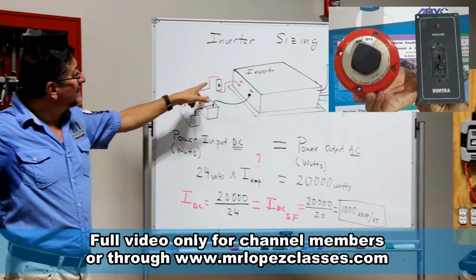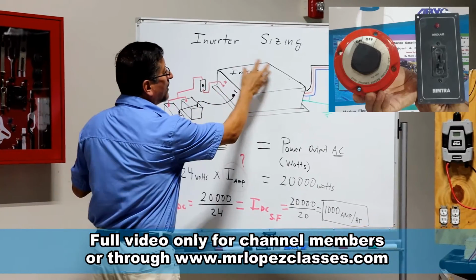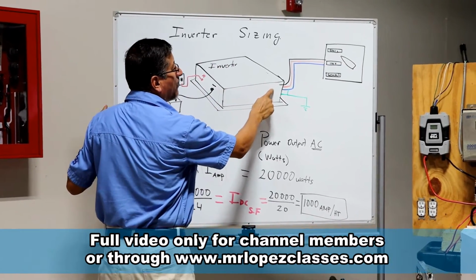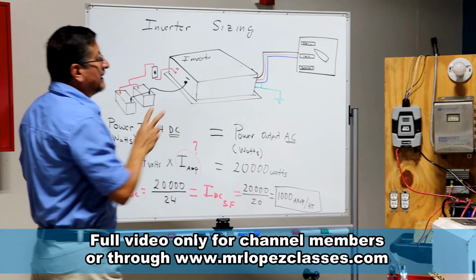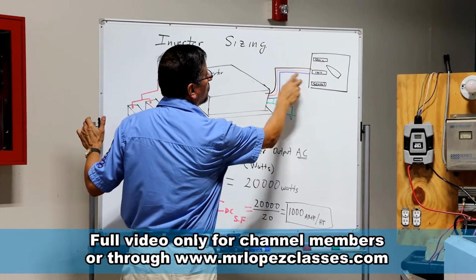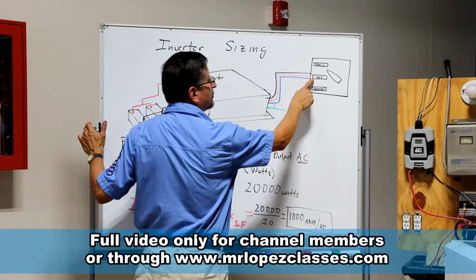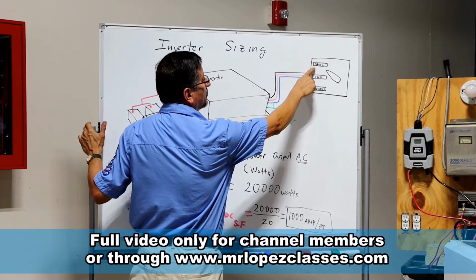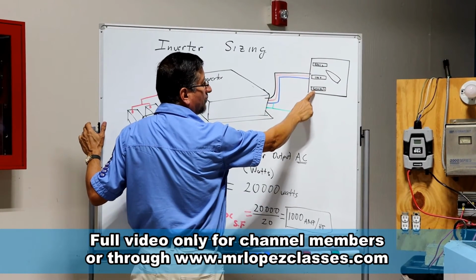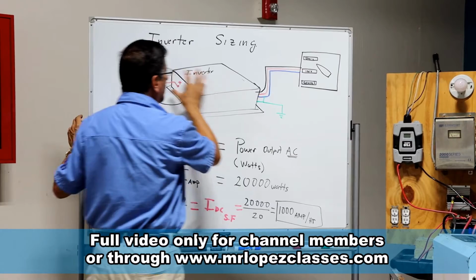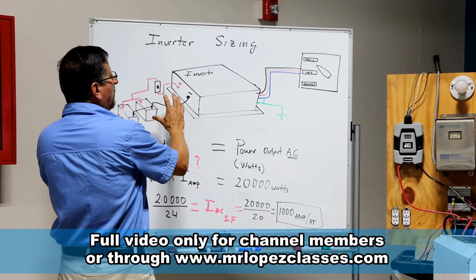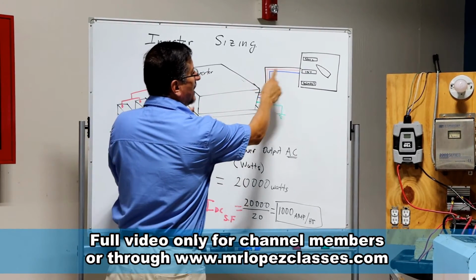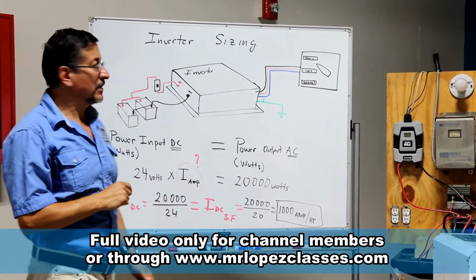The input DC power enters into the inverter, and the inverter converts the power into AC power. That source of AC power goes into the switch selector in the position inverter. There are other positions for shore power and for generator. In this particular case, the DC power is converted into AC and enters in the position inverter.